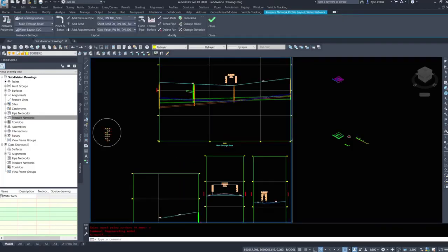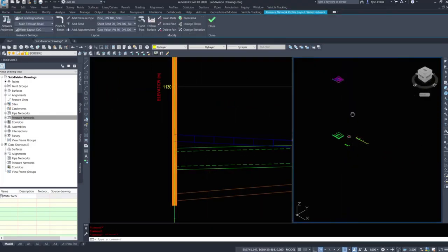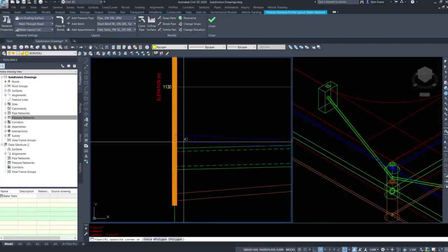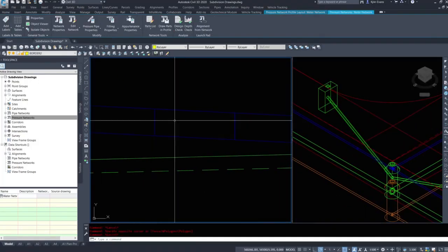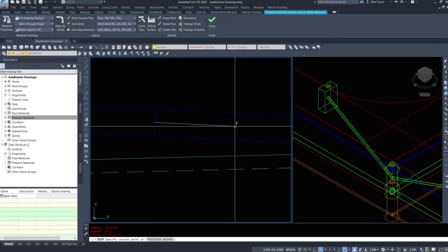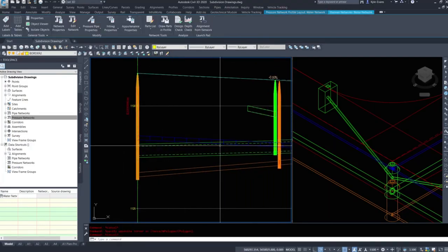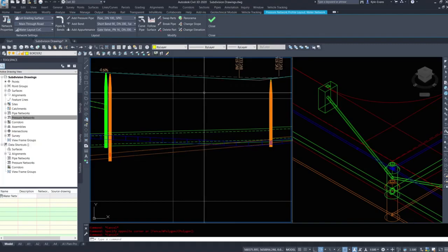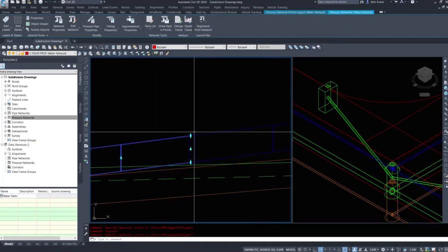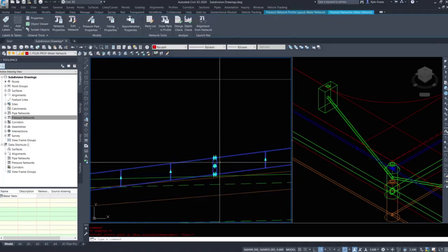It's shrunk my profile back down. And if we look at our pipes now, that one no longer goes down to 0. We now have a break. And if I measure this distance, it should say 6 meters based on what we typed in that previous document. So 6 meters. Civil 3D follows that surface with your pipe. So this pipe will be exactly 3 meters underground. And we can modify things. I can select these objects. I can move these objects up and down.